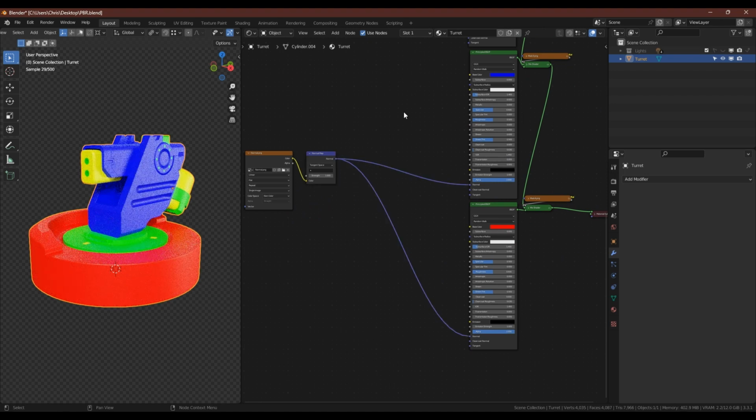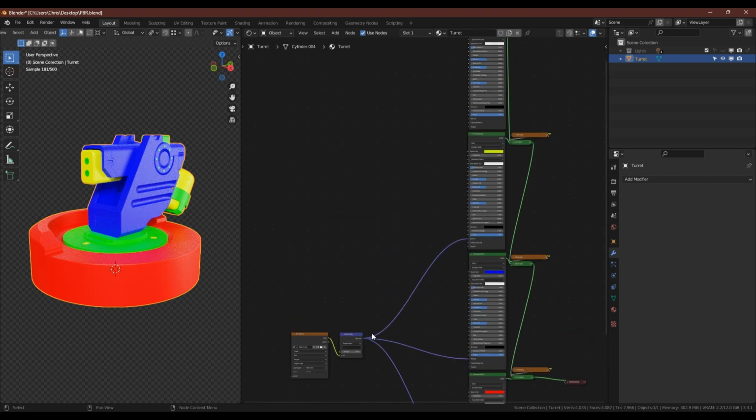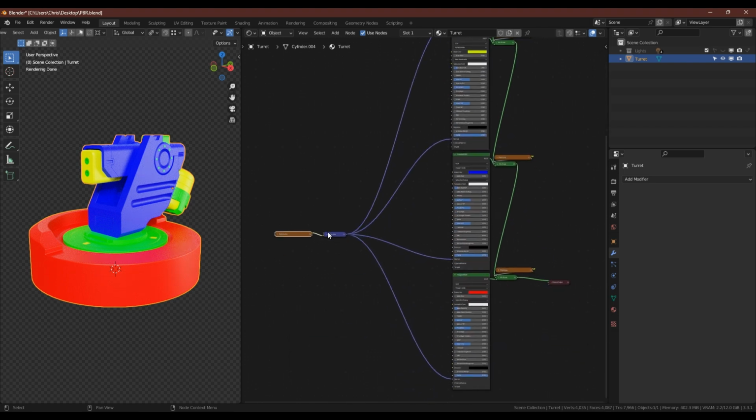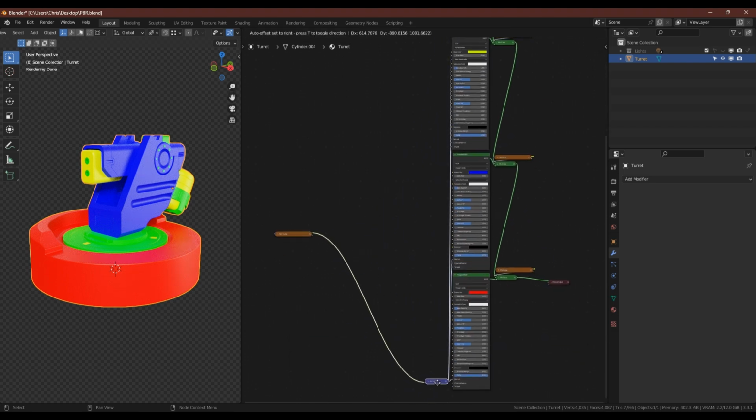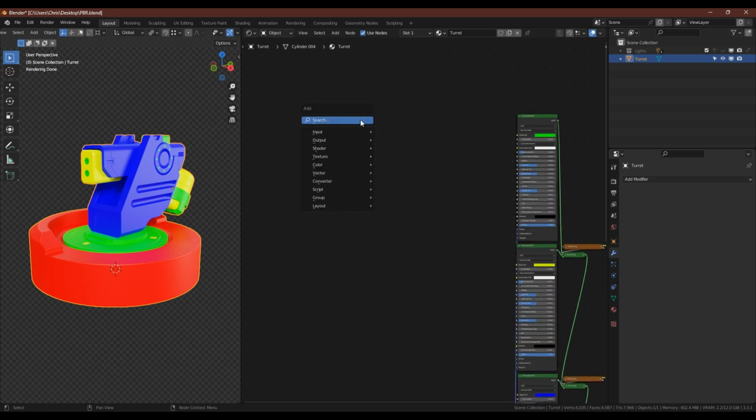And you'll see as I do this, everything on the actual model will get beveled, and you'll start to see all the panel lines and surface details that are everywhere. I'm going to put this down here for now. We may need to add to that if we've got anything that has height data. We can run that normal map through a bump node as well.